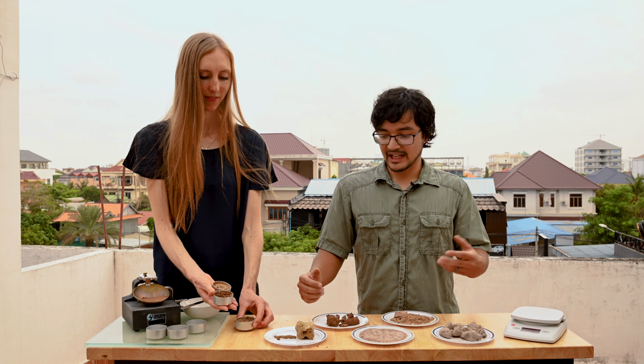One thing that you might also want to note is the odor of the soil. The odor of the soil might give an indication of the presence of things such as organics, or if there's a chemical smell, it might indicate that there's some pollutants such as gasoline or petroleum.